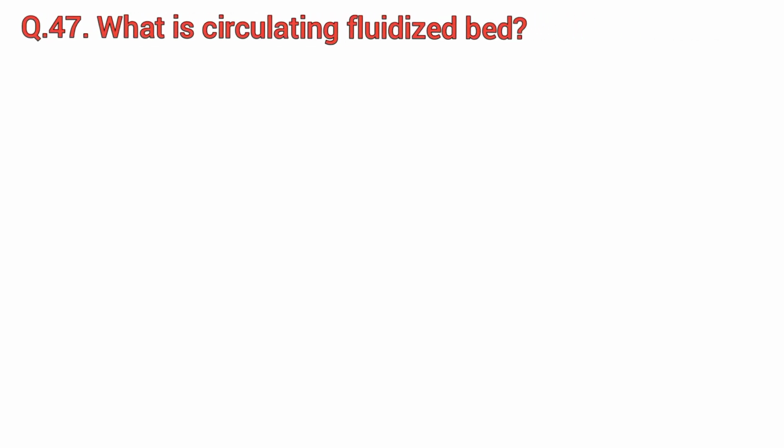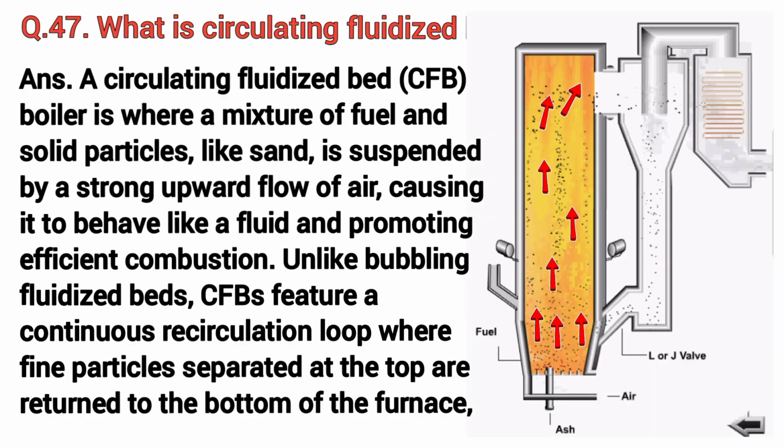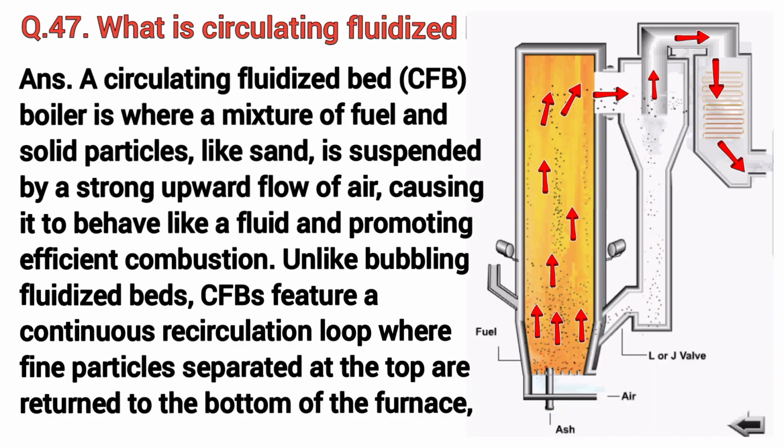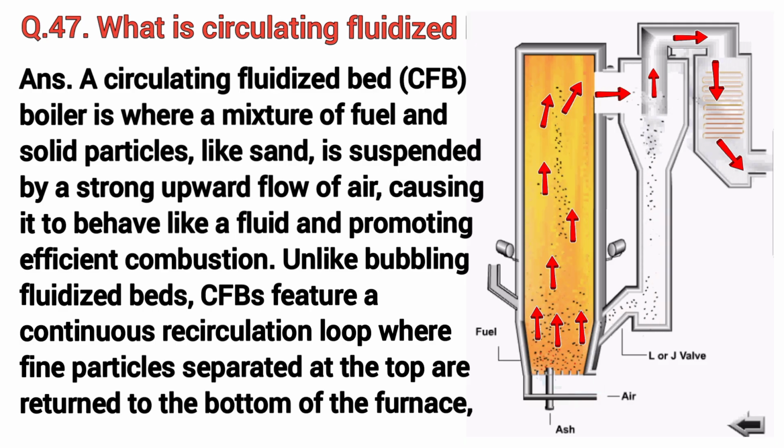What is a circulating fluidized bed? A circulating fluidized bed, CFB, boiler is where a mixture of fuel and solid particles, like sand, is suspended by a strong upward flow of air, causing it to behave like a fluid and promoting efficient combustion.